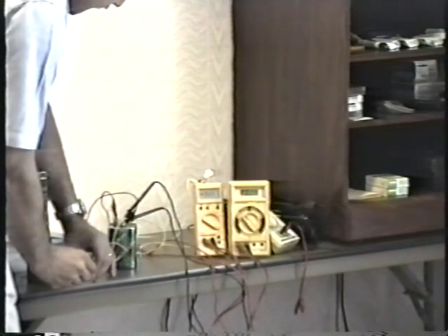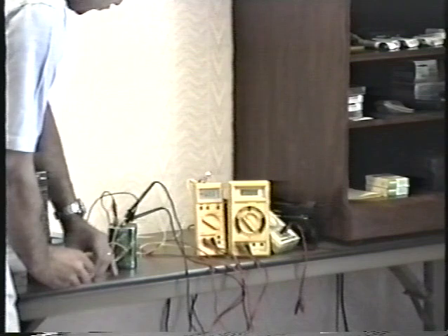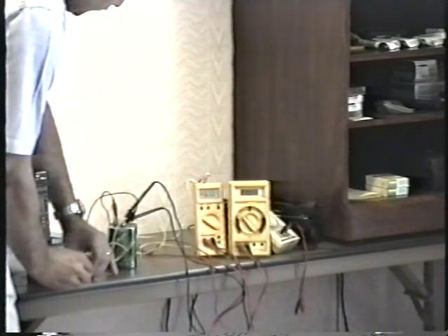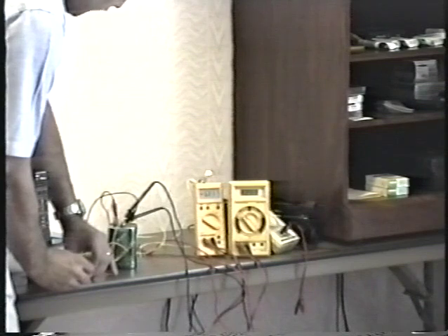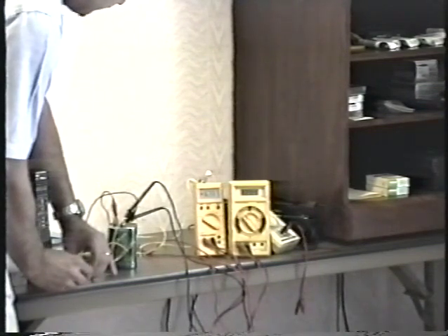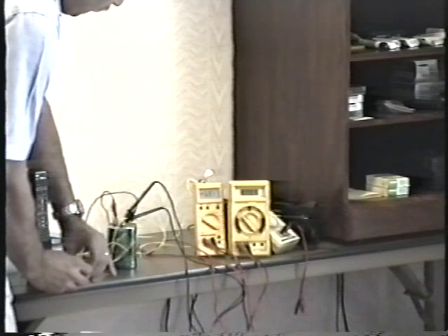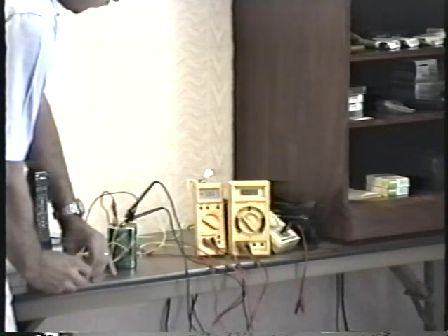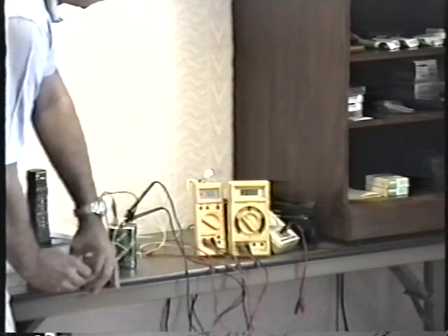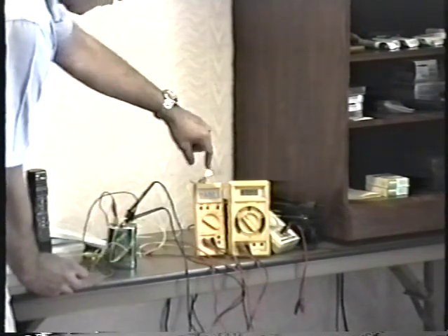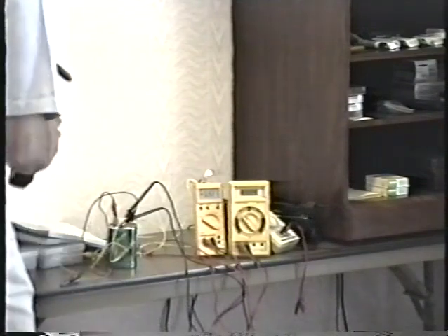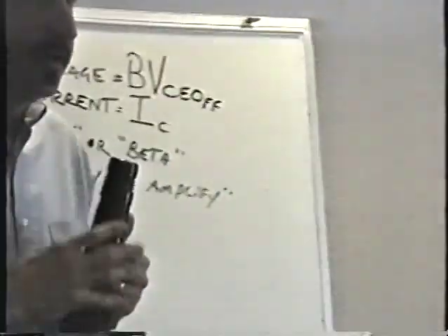You know how, when we were doing this experiment over here, the tiniest change in voltage on the base produced this much larger change on the collector. At 0.66, the thing was dim, but at 0.7, just 40 hundredths of a volt later, it was up full bright, and we had the collector drop to 0 volts. It only takes a fraction of a volt change on the base to produce a much larger change between the collector and the emitter.